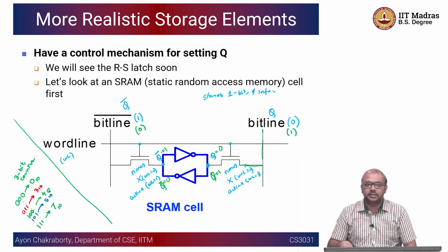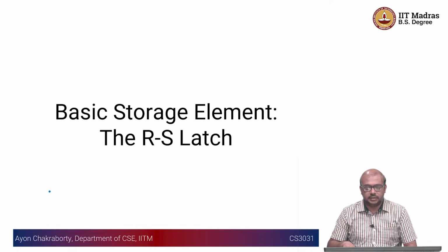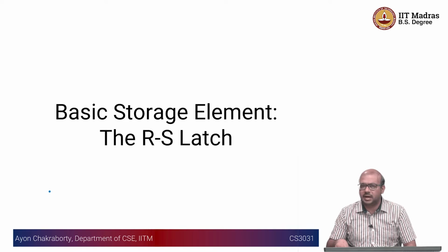A latch is basically once you put a value, it gets locked, right? Like a door latch. Okay, so that is why it is called a latch. And we will start with that as the first basic storage element called the R-S latch. You will find many book references where they are also called SR latch.